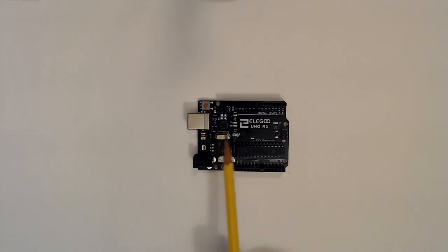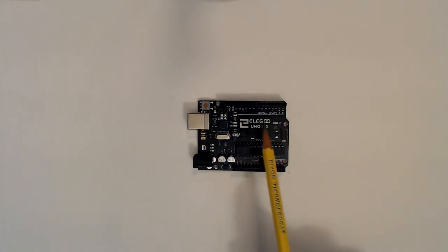They consist of many different input and output terminals. For this video, we'll focus just on the output terminals, and in some later videos, we'll discuss the inputs. The output terminals, like they sound, are outputs of the device. For a lot of them, they're just going to be simple switches, switching it either on or off. When I say switching it on or off, what I mean is if you take a look at one of the channels, say this pin here, this pin can be either 0 volts, which would be off, or it could be 5 volts, which would be on.